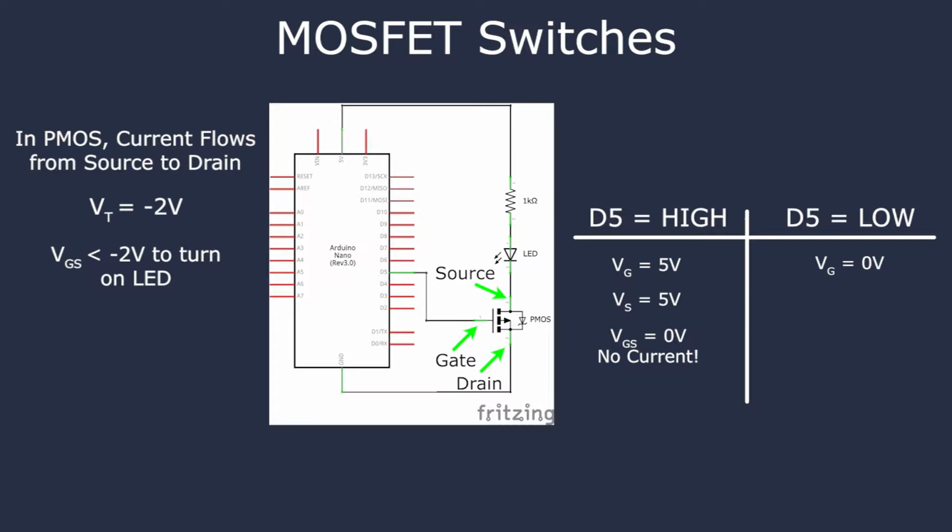The exact equations and reasoning behind this are a little complex, so we'll try a simpler explanation. Let's pretend that the transistor is fully on, and model it as a resistor of about 0.05 ohms. This isn't an unreasonable assumption, if the transistor is actually fully on. Now, almost all of the voltage is lost across the LED and resistor due to their much higher resistance than that of the PMOS. That means that there's almost 0 volts to be lost across the 0.05 ohm resistor. Therein lies the problem.